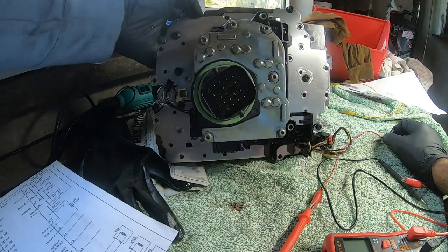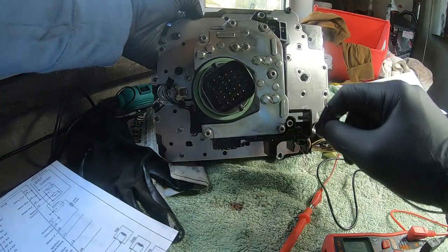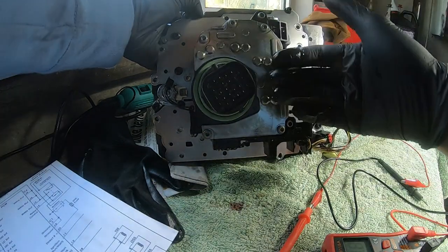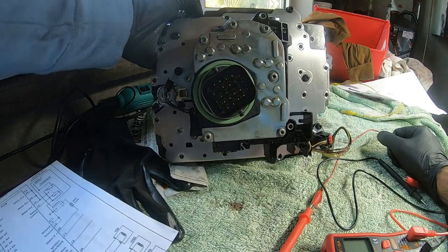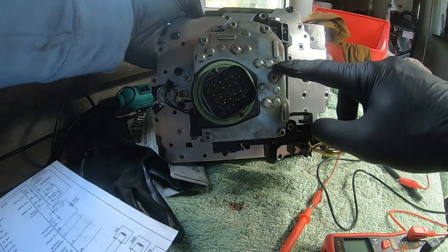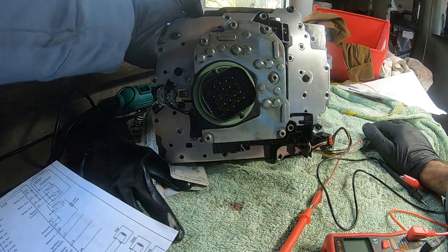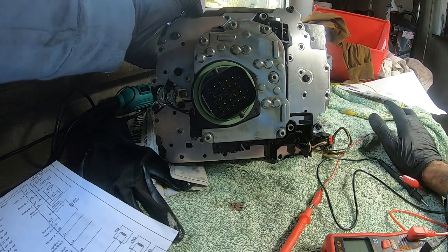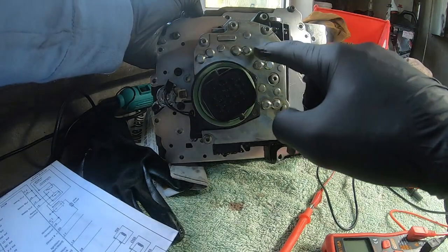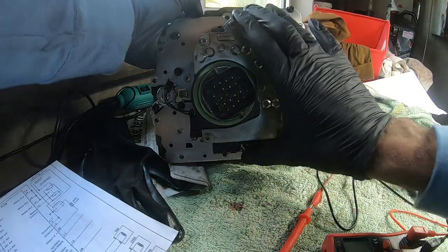Right off the bat, what we can see here is that it has 6 bolts on this plate, and it is spring loaded, which means that if you remove this plate, there are springs behind it trying to push it forward. These springs are located here, 1 2 3 4 5, and all these springs, as we discussed, belong to those pressure contact switches or clapper valves. Also, these bulges over here are the pins for the solenoids that are behind it.